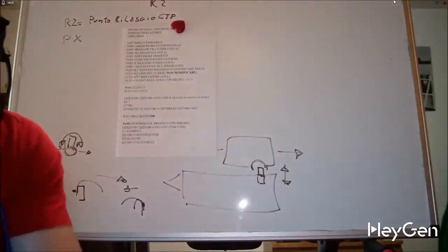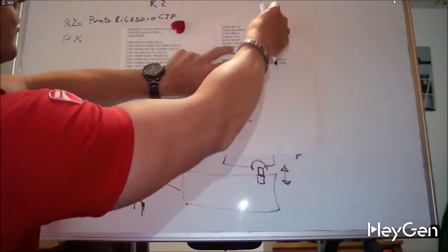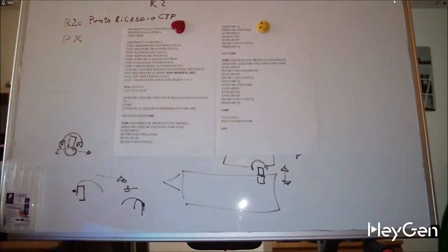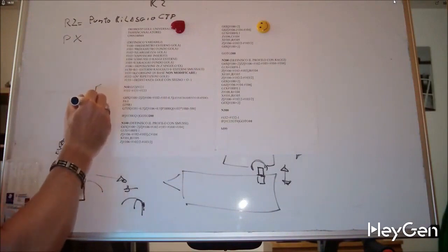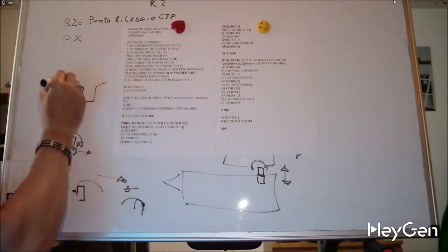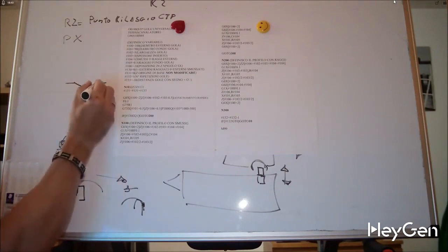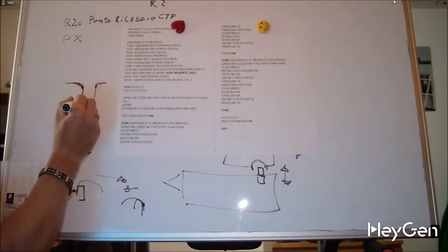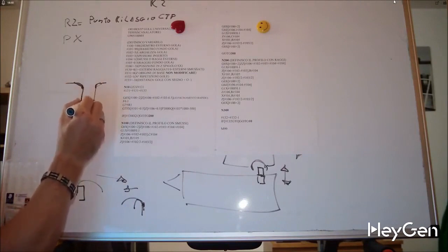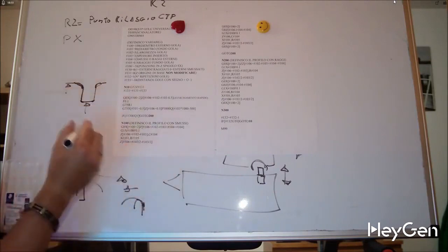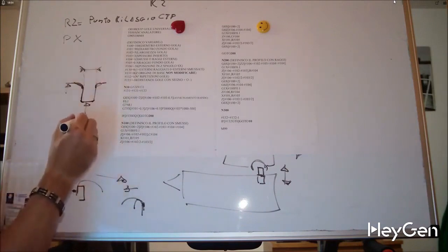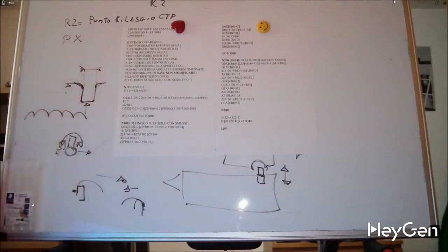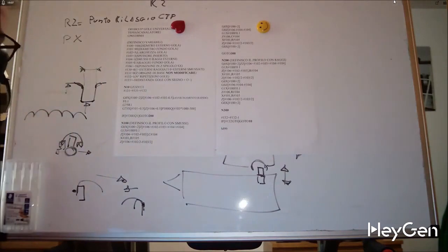Origin. This is a subprogram to decide whether to create a groove along an outer diameter that has chamfers or radii with a bottom groove radius of a certain size, a starting diameter, and a bottom diameter determined by the variables, a width determined by the variables. And this groove can be repeated as many times as I want along the arc of my outer diameter.